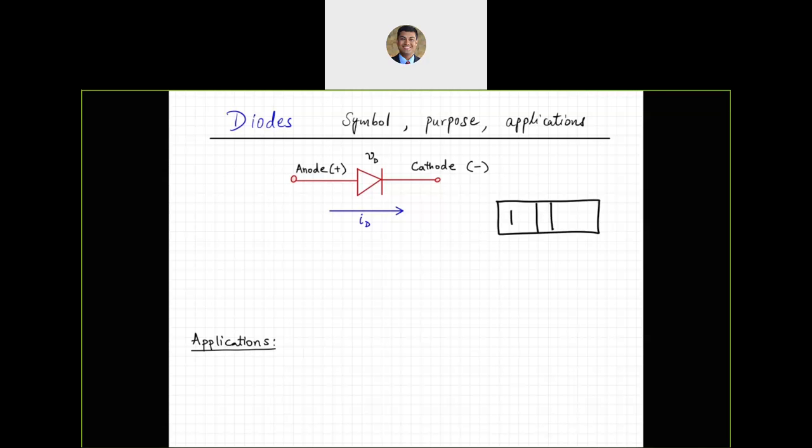One is of p type and one is of n type. All that means is the p type has excess holes, and the n type semiconductor has excess electrons or excess negative charge. And in the middle over there is an intrinsic layer. We call that the depletion layer.